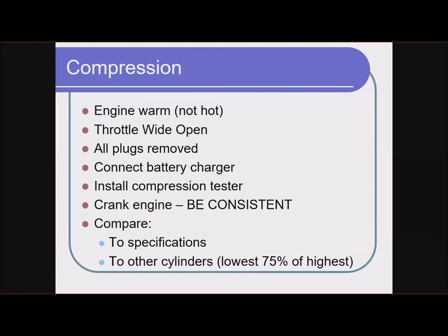What we want to do is do each cylinder twice and then average the 2 readings you get. Compare those readings to specifications and compare every cylinder to the other cylinders. The lowest cylinder should have at least 75% of what the highest cylinder has.